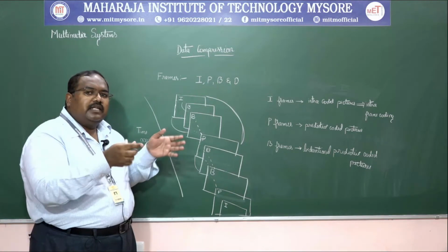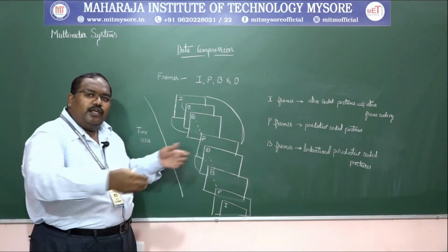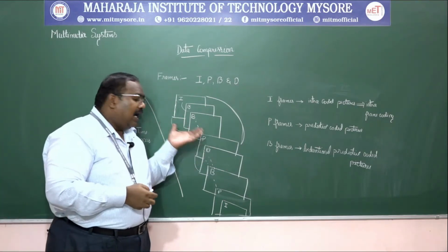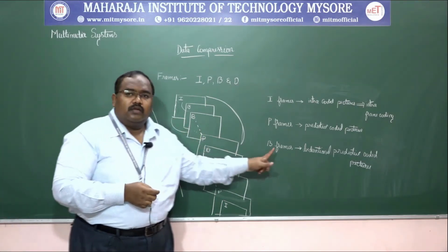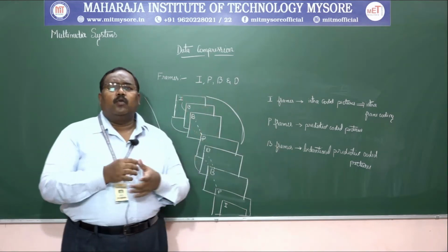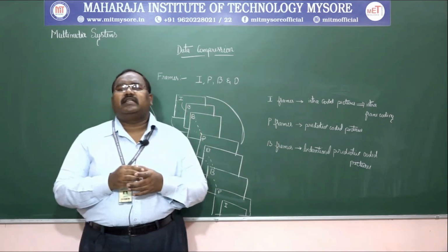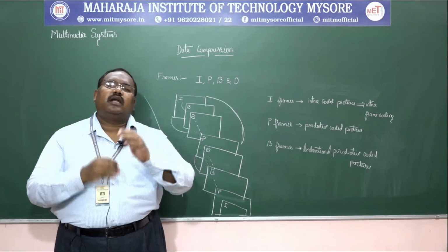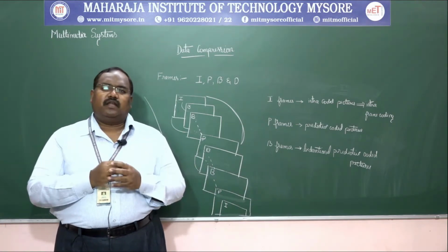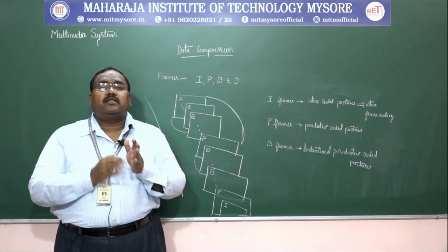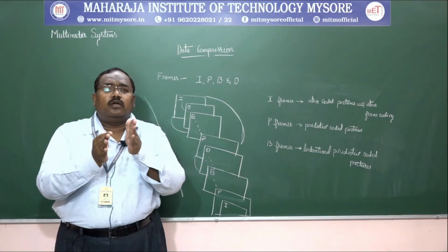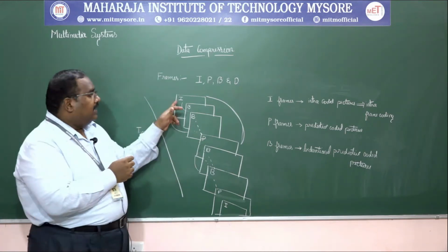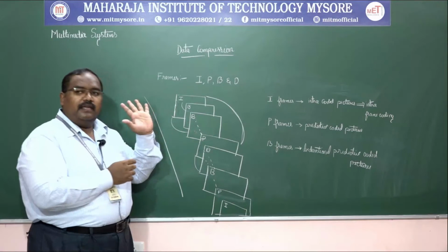When we decompress it, those predictions can be applied and a new data stream can be achieved. That is why we have a high rate of data compression with respect to B frames. A B frame is defined as a difference from a prediction based on a previous or a following I frame or a P frame. What I said exactly means it is directly followed, or a prediction done based on either an I or a P frame.